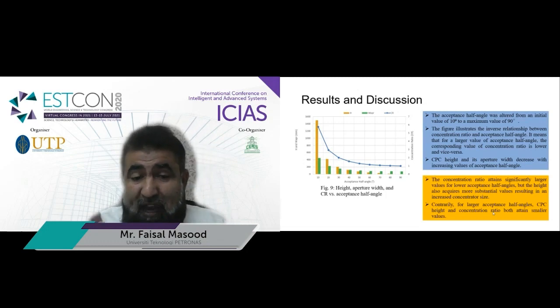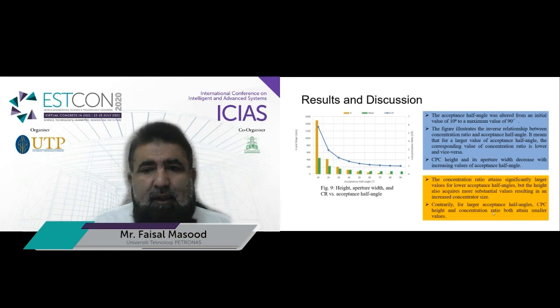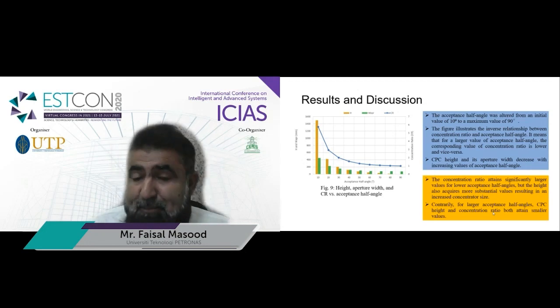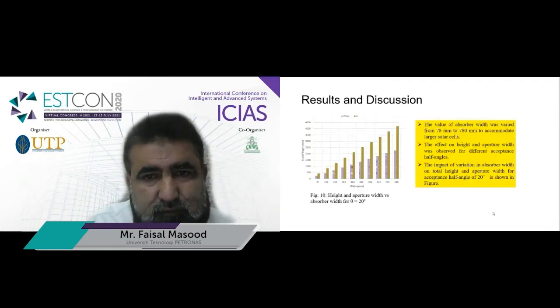So actually we have to choose a value of acceptance angle for which we can obtain a suitable concentration ratio and lesser height. When the concentration ratio is maximum, the CPC height is too much.